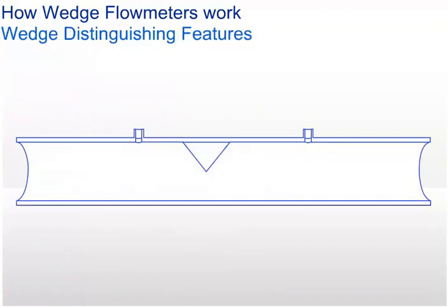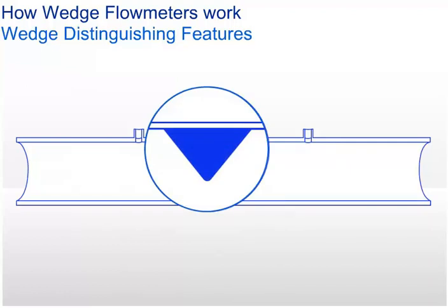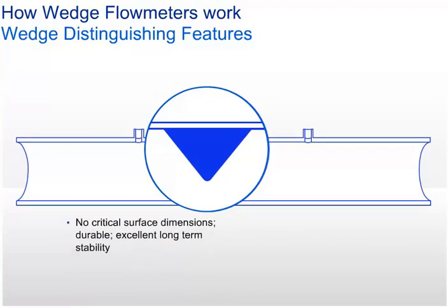The wedge element has no moving parts. This means the wedge will have lower annual maintenance costs than devices such as the turbine meter or positive displacement meter. The V element has been designed without any sharp, wear-sensitive surfaces, which means the meter will not suffer any significant dimensional changes under normal wear, even with erosive solids in the fluid stream.